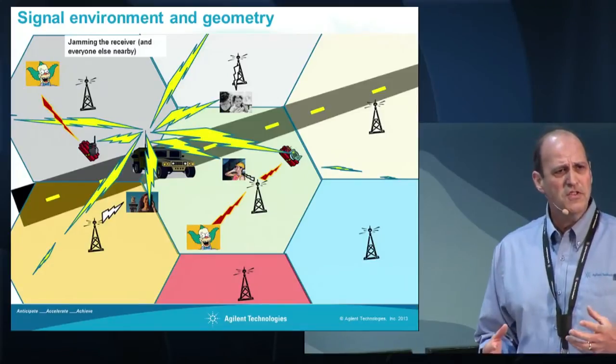Generally speaking, most of these signals that might be used perhaps to detonate an IED would be in the 0 to 6 gigahertz frequency range. It's much, much less common for, say, microwave signals to be used for these purposes. So the idea is to try to look in all directions. Generally these would be omnidirectional systems that you might use to jam, since the signal could come from any direction. And you're obviously trying to do the best job you can to evaluate as many signals as possible and act very quickly to be effective.